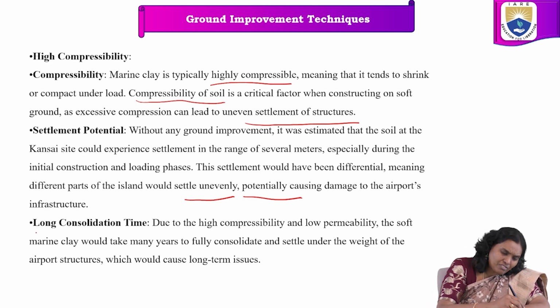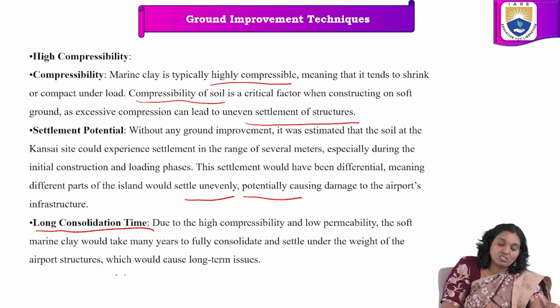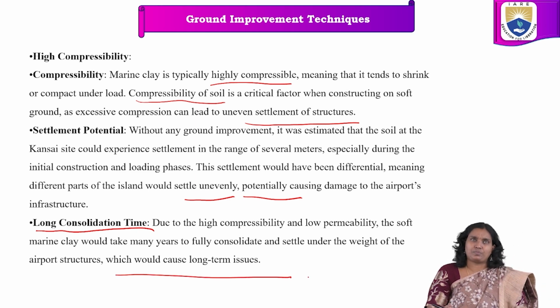As a part of long consolidation time, due to high compressibility and low permeability, the soft marine clay would take many years to fully consolidate and settle under the weight of the airport structures, which would cause long-term issues.